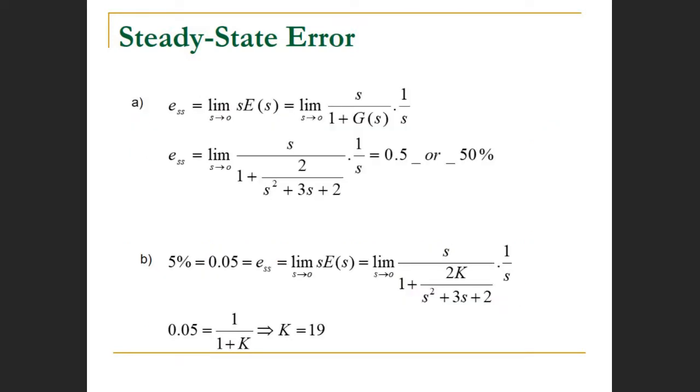So let's see the solution. Again, we clearly remember the formula for the steady state error, and we're talking about a unity step input. So we're now applying the formula S over 1 plus G of S all times 1 over S. And so we're now going to notice the substitution that we're going to be doing. So carefully note that we have S in the numerator, 1 plus, we're putting the transfer function now, G, the forward path transfer function, multiplied by 1 over S.